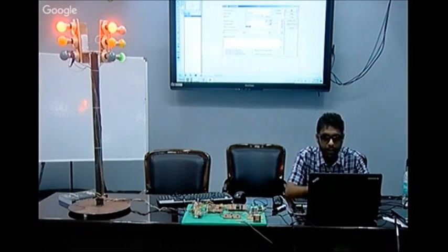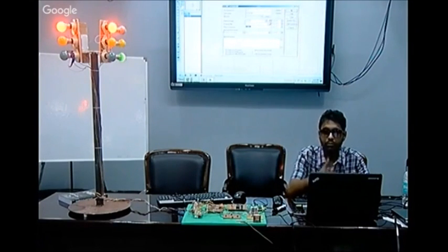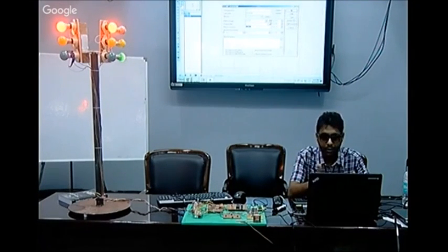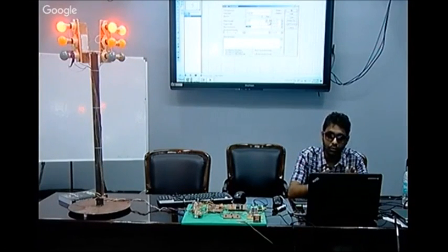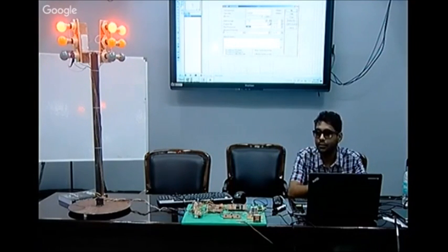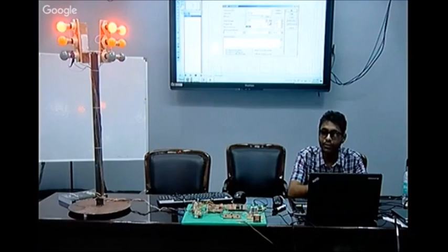This is a very important parameter, clock frequency. For example, you want to do a real-time simulation. You write a program in a computer to generate a delay of 1 second. When you write that program in hardware, it will show you 1 second. But if you run that program in Proteus, it will not show you 1 second. Error is due to this frequency.